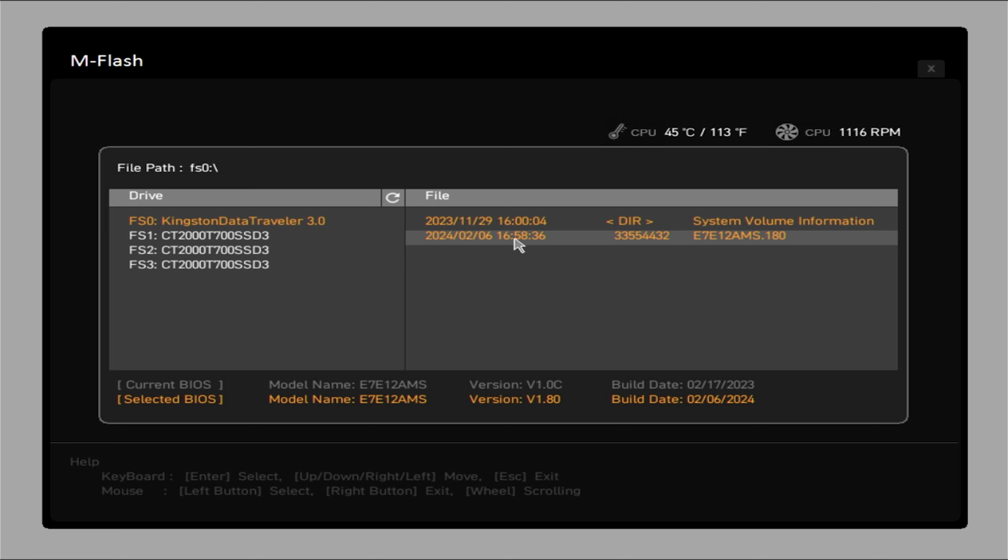If your motherboard restarts, it will probably automatically detect the fan and do what it needs to do. But our fan is a 4-pin PWM fan. So the first thing that we should talk about is the settings over here. So PWM and DC. So DC is basically sending a voltage to your fan, and that's it.